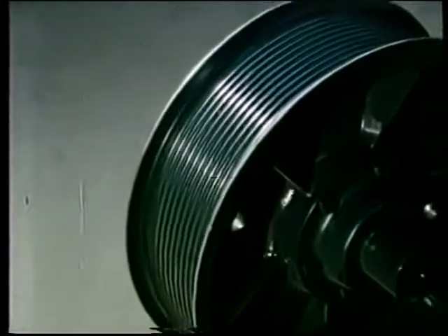This specification requires a minimum ratio between rope diameter and sheave diameter of 40:1. In the case of this machine, the sheave diameter was 910 millimeters, and we decided to use a rope of 16 millimeter in diameter. And thus you will see we achieved a rope to sheave diameter ratio of about 52:1, well in excess of the 40:1 required in this specification.